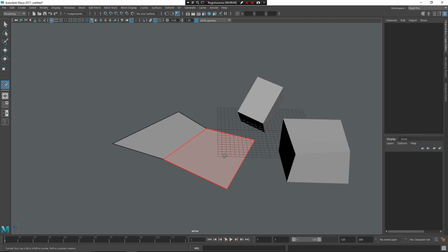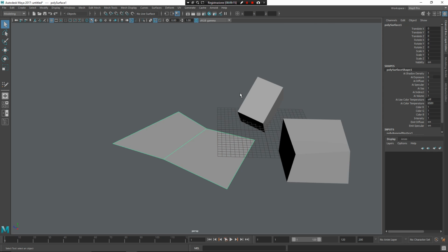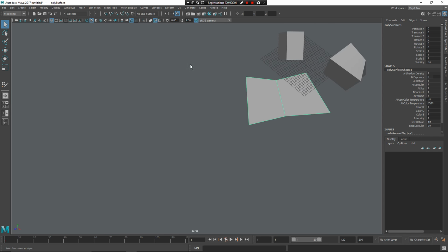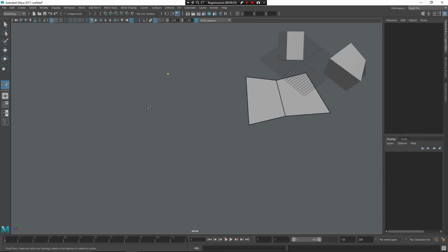Now look at this. I press Z and the middle mouse button. I have the ability to use Z, middle mouse button, contextual marquee menu for the tool in this case, and I can complete my tool. This is similar to pushing Enter. Or for example, if I create too many dots, I can press Z, middle mouse button, and clear dots.